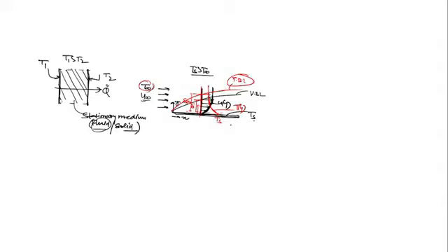Why will the heat transfer initiate here? Because any layer of the fluid just on the surface, listen, the first layer of the fluid which is on the surface of the solid will be at the temperature Ts, but any other layer of the fluid is at a different temperature, and that temperature difference in the fluid causes a temperature gradient, and due to this temperature gradient energy gets transferred, and that energy transfer is through convection, not conduction. Why not conduction? Because the fluid is in motion. Yes or no? Here, listen, the surface temperature differs from the fluid flowing. Ts is more than T infinity.